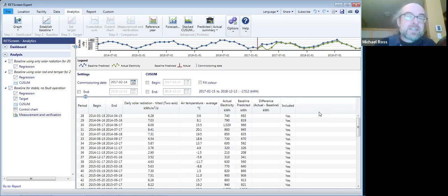The good thing is the energy curve, not the power curve, but the energy curve, which expresses the output of your wind farm as a function of the average wind speed. So if you're saying the annual average wind speed is X, it provides the energy that would be produced over the year. That tends to be a bit more linear. And even if it wasn't linear, you might be able to fit a nonlinear equation to it. But it's not as straightforward as with solar photovoltaic projects.